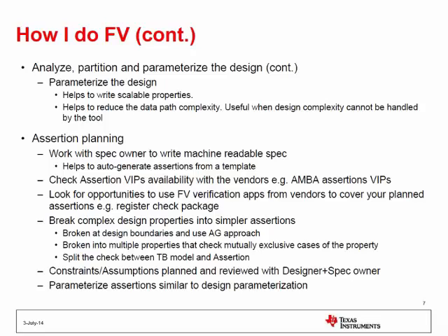If you are able to get a spec writer to give you the spec in some standard machine readable form, then you can actually process that machine readable form, use an assertion template and dump out auto assertions and then apply them on your design. I'll show some examples where we have found this useful. Again, you need to work with the spec guys to make sure they're writing in a form that is machine readable. And check if verification IPs are already available for assertions.